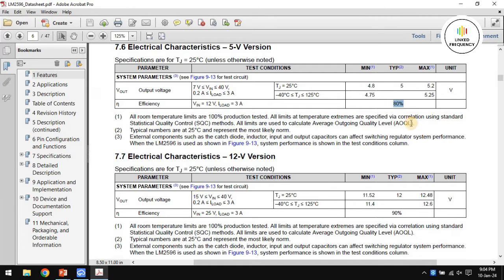What does this 80% mean actually, and what is the difference between this one and your linear voltage regulator, which is the 7805, right? The 7805 has somewhere around 41% or 42% efficiency, very low and very outdated in industry. However, this one is 80% efficiency. Still, it is not a good one. Again, we have a 95% efficiency buck converter in the industry, but they are too costly. That's why we go with this one, as 80% is sufficient, much better than the 41% or 42%.